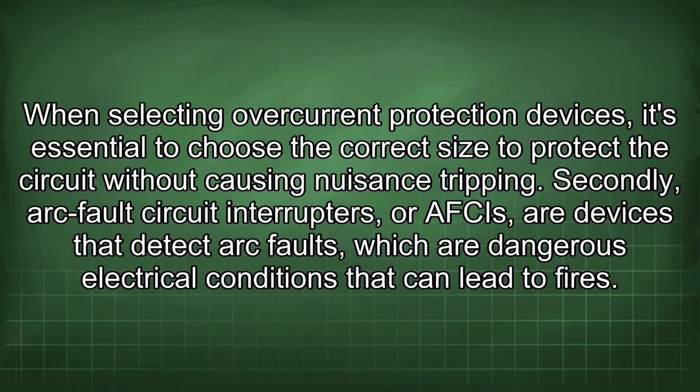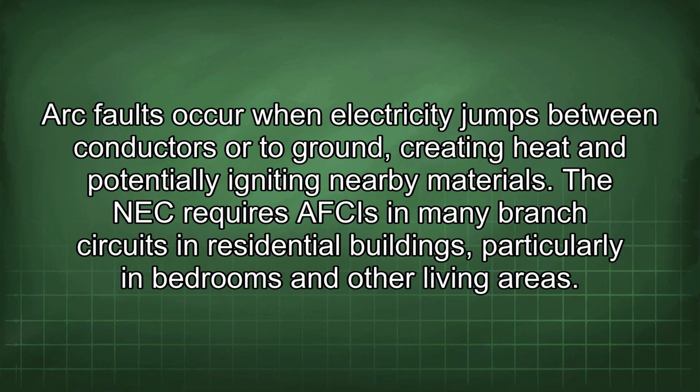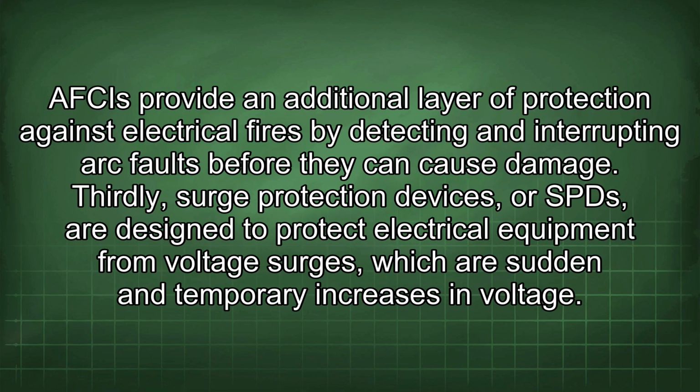Secondly, arc fault circuit interrupters, or AFCIs, are devices that detect arc faults, which are dangerous electrical conditions that can lead to fires. Arc faults occur when electricity jumps between conductors or to ground, creating heat and potentially igniting nearby materials. The NEC requires AFCIs in many branch circuits in residential buildings, particularly in bedrooms and other living areas. AFCIs provide an additional layer of protection against electrical fires by detecting and interrupting arc faults before they can cause damage.